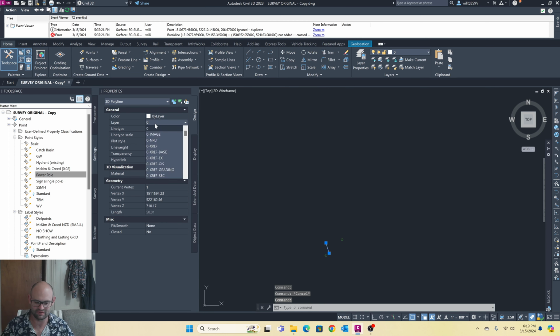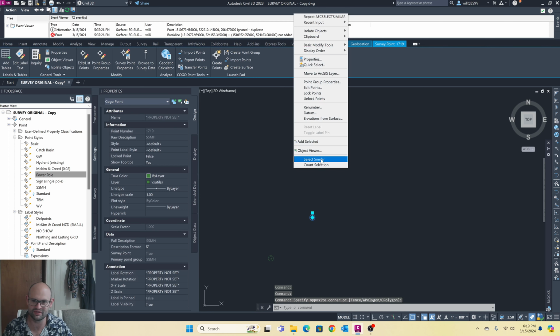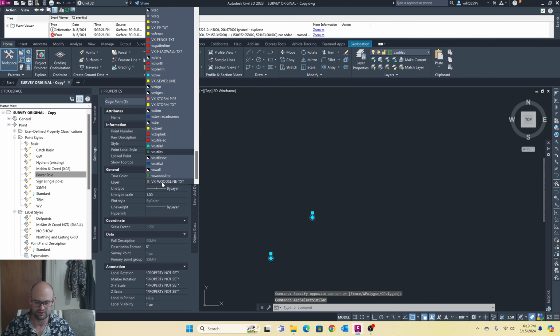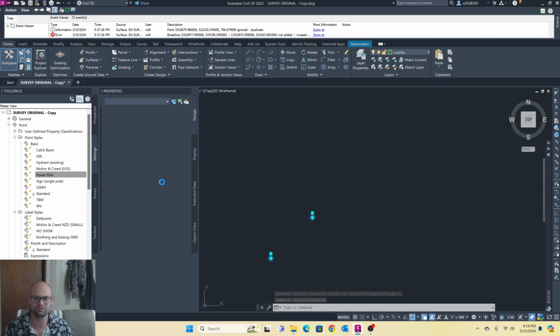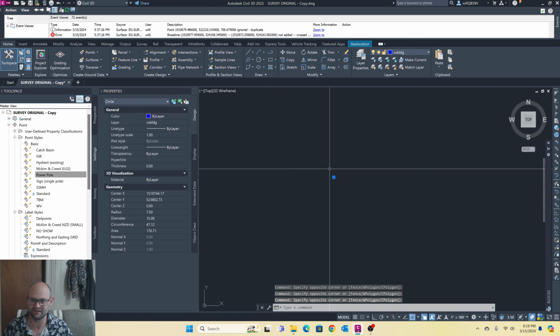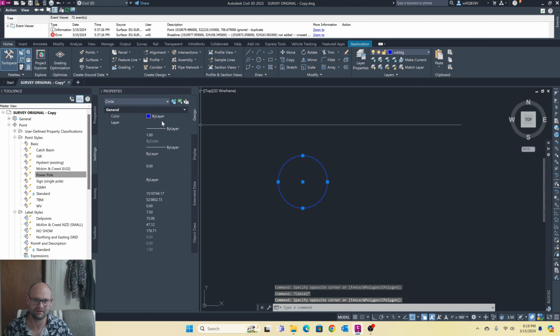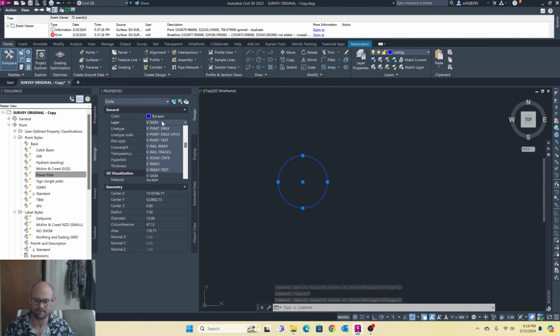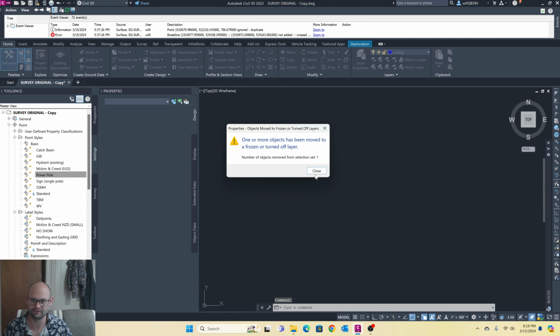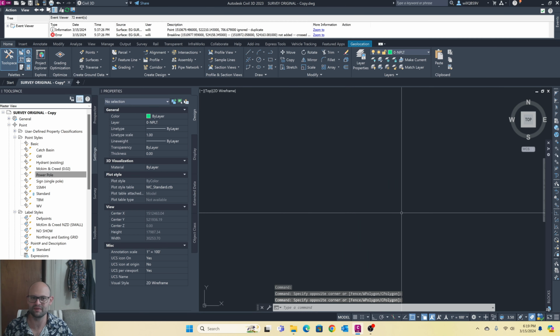This was a pipe, a storm pipe. The inner piece of it though. We already moved the outer walls. Got some manholes here. Select similar. V sanitary sewer dash structure. Now, what's left here? Something right here, a circle. Existing building. Let's go V dash building outline. See if there's anything else. Nothing else can be seen now.